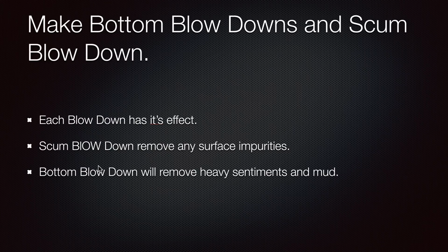The preheating of the line is just to make sure that you will not stress the line and you will not damage the flanges or the gaskets. That's why we always make it like that. We let the steam flow heat the lines, but it's not always the case. But with that solution and with that trick, you'll prevent a lot of problems to the lines and prevent the gaskets from being damaged.